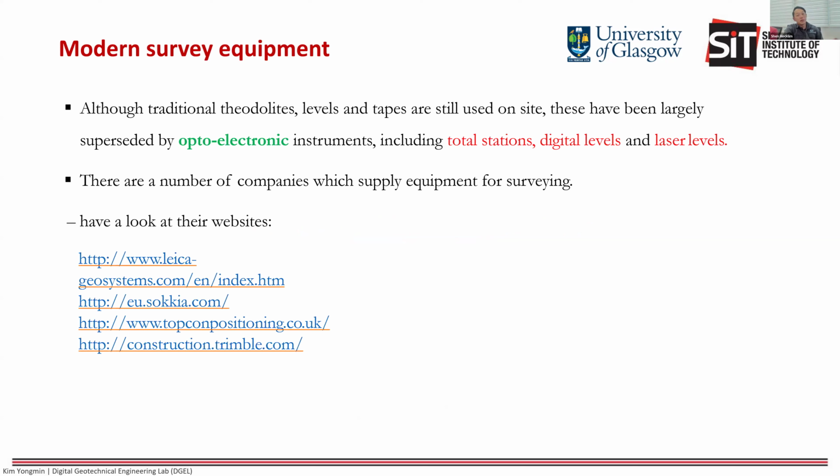But right now, there's been a big shift to knowledge about total stations, digital levels, laser levels, and these are much more productive. If you know how to use them, your ability as a civil engineer can be multiplied. Each tool actually addresses a different need. We generally group them according to degree of accuracy. For example, if you use a digital level, you want it for checking the heights and the levels, but you can't use it to calculate bearing.